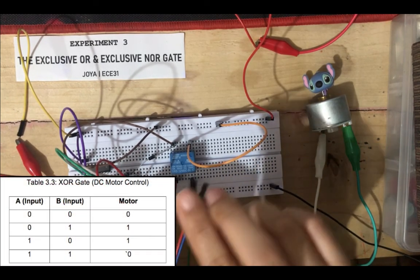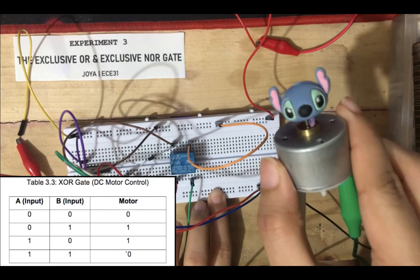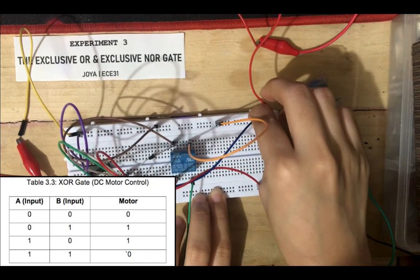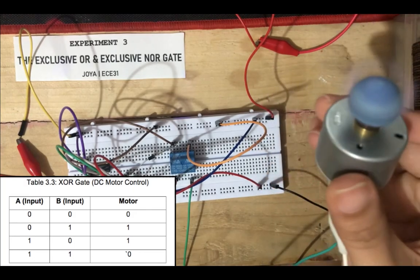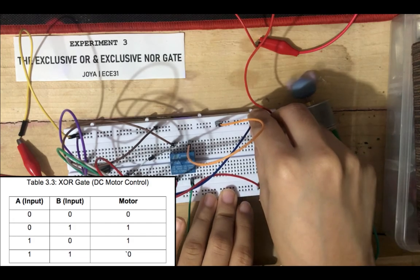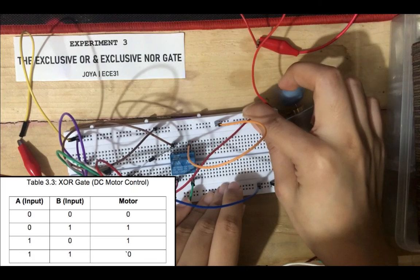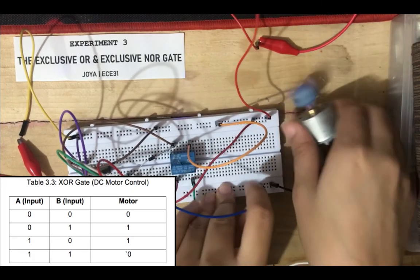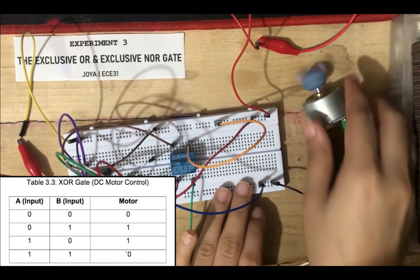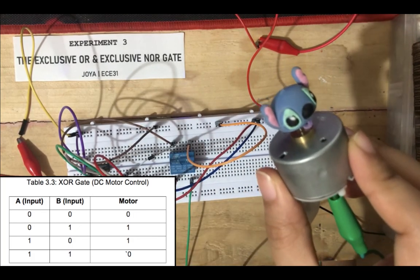So if I connect A and B to 0, let's observe that output is 0. And if I connect B to 1, it's observed that output is 1. So now I'm going to connect A to 1 and B to 0. It's observed that output is 1. And if I connect both inputs A and B to 1, output is 0.